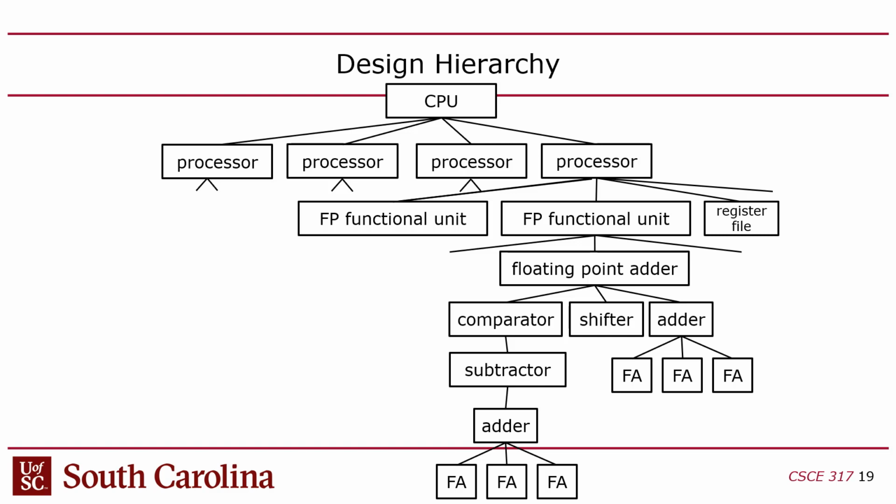You will never know how fast that C code runs. It's impossible, because there's cache misses, there's interrupts, there's all kinds of non-deterministic things that happen. So you'll never be able to truly have a real-time system in software, because you'll never really know what the worst-case execution time is, because it's impossible to account for all of these cache misses and page table misses, page faults and interrupts and all the things that go on with the CPU.